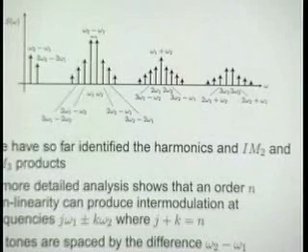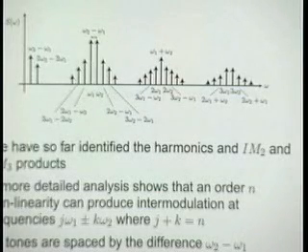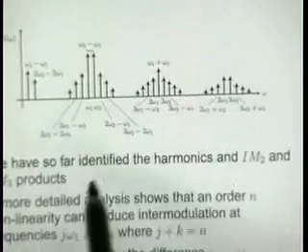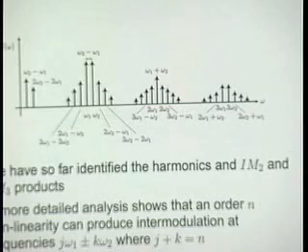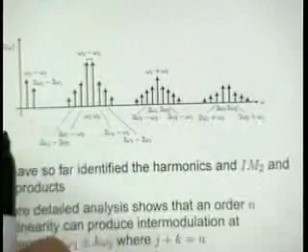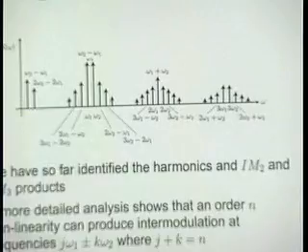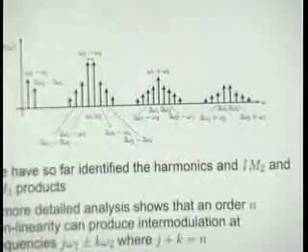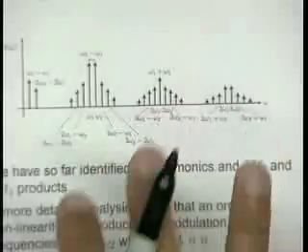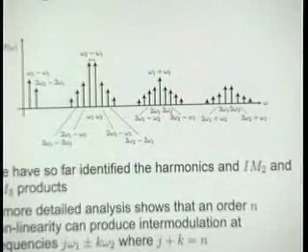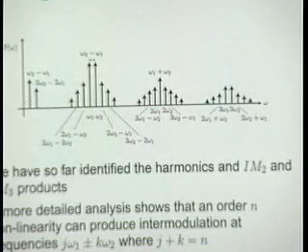So it's interesting. I encourage you guys to go and look on the spectrum analyzer. Take a nice innocent looking amplifier, put 2 tones in it, and look at the output spectrum, and you'll see something like this. And no matter how small you make the signals, there always will be this distortion present. It's just usually so small that it's below the noise floor. You don't notice it. But if you turn up the signals, eventually they'll creep up above the noise floor and they'll start hurting you. Okay? Questions?